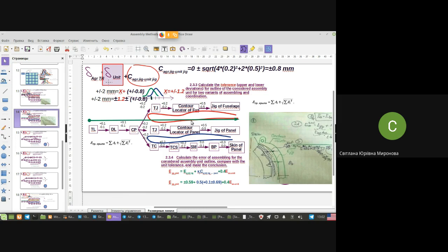For flat units, for inner units of an airplane, like frames, like ribs, especially the ribs that you have, which have compensators and do not touch the contours of the wing, it's quite enough to have such accuracy, because next you're going to compensate it in real life. But in your bachelor work, of course, you need to do everything inside tolerance, and it means that it's not appropriate to use this technique of coordination.